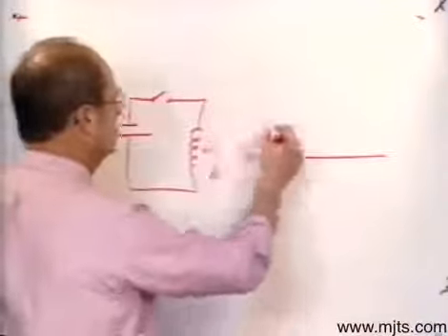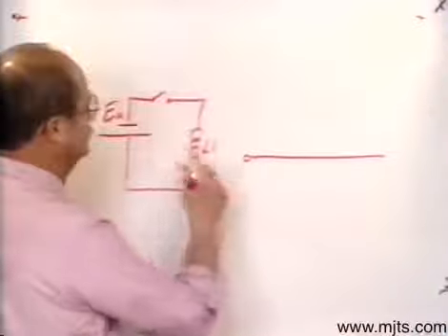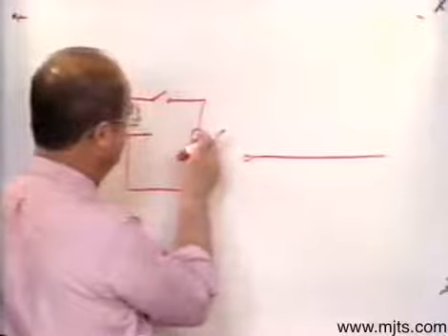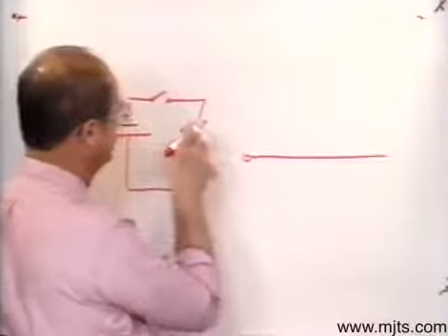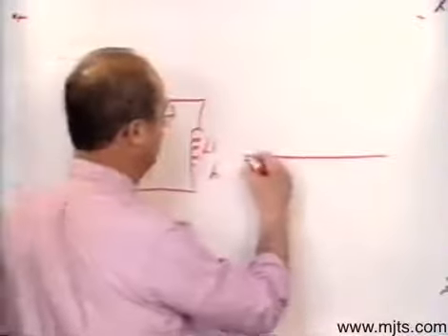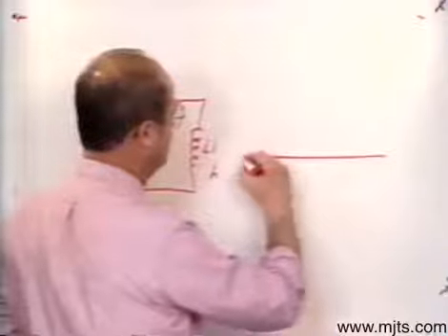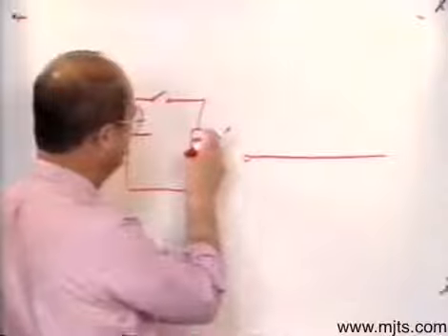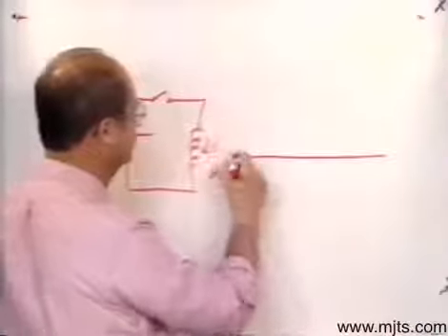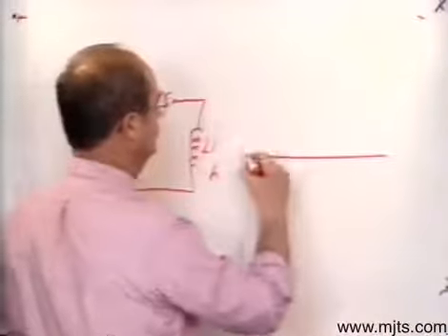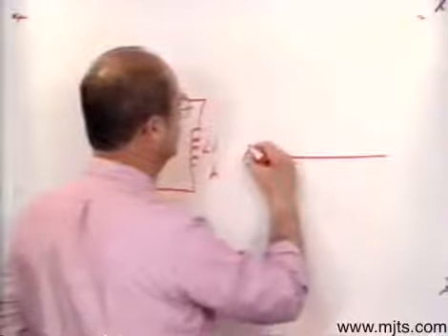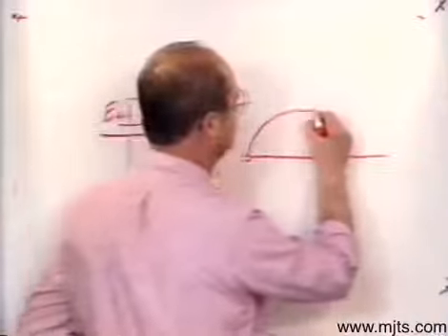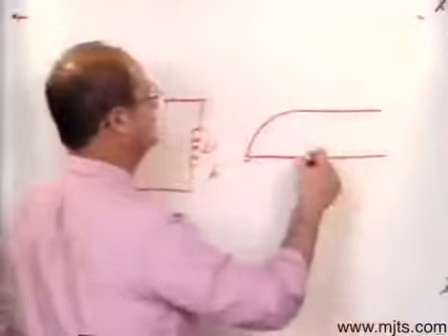The way this would look, if I close this switch, is that because I'm getting a changing magnetic field, the instant I close that switch, my current flow is going to try and build up to a maximum, but because of the induced counter electromotive force, it doesn't instantaneously go to the maximum. It'll go through what we call time current curves till it reaches its maximum, then it levels off at maximum.